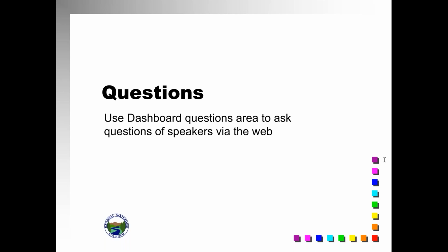But my pat answer is no, you need to remove all the vegetation. Because even if it is a big healthy tree, what happens if there's a gust of wind and the ground's saturated and it takes a big clump of dirt with it, especially if it's at the toe of the dam or at the crest of the dam? That's a serious problem at an embankment dam. So my advice is to remove it.